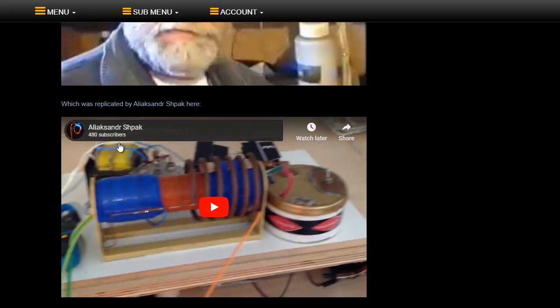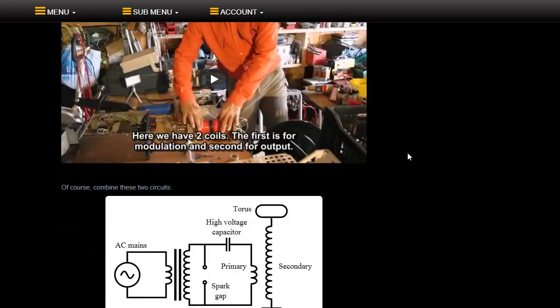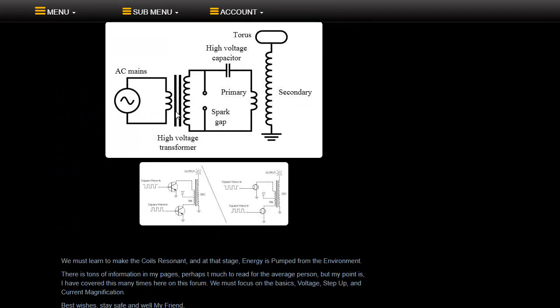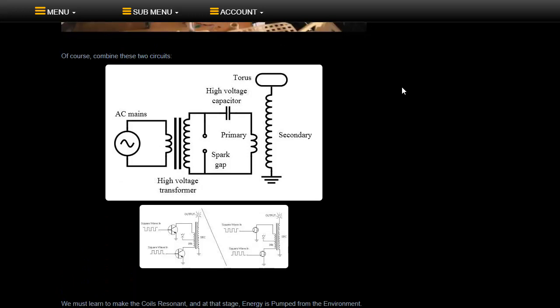Now it's possible this transformer here, I don't know this for sure, okay, I haven't seen inside this box here, is that transformer there, because remember what I said before, Terrell Capanazzi, most of his units were at 50 Hertz, so a large transformer like that would be fine at 50 Hertz. It wouldn't be okay at say 37 kilohertz. So 37 kilohertz, if that's what you want to do, that would need to be a ferrite transformer, which is the same as what Ruslan shows many times.